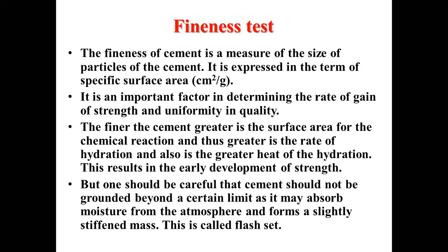Flash means, like when you take a camera and click, the flash comes out in a fraction of a second. Like that, here also the cement sets very fast and breaks, so cracks develop. That's why flash setting properties are always to be avoided. If you go for very fine cement, this is the disadvantage we get: the flash set of the cement.